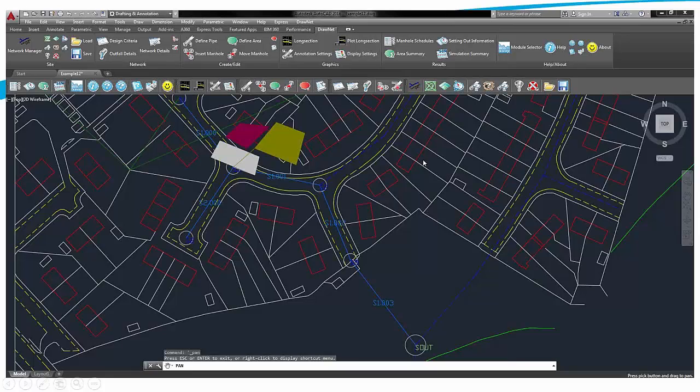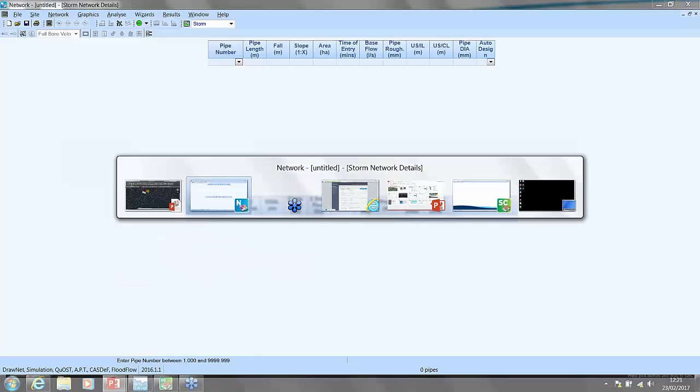And what this slide also demonstrates is that MicroDrainage has a very specific numbering system. The first pipe in our system must be pipe 1. Any branch that comes in must be numbered consecutively, so branch 2. And then as we move downstream, we add the suffix number. So 1001, 1002, 1003, etc. as we go down the system. Again, that takes some learning and some getting used to, but just for now, understand that there is a very specific numbering system that we have to stick with.